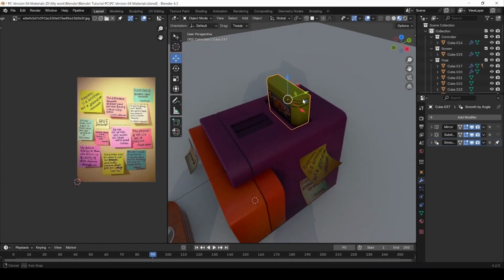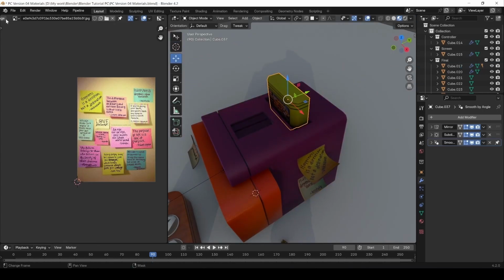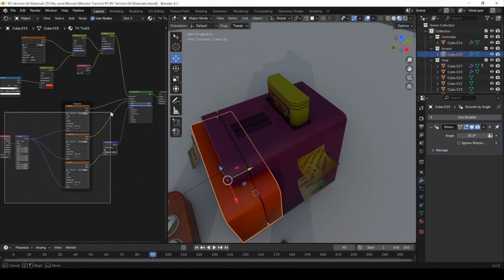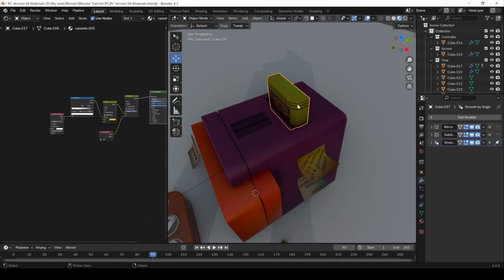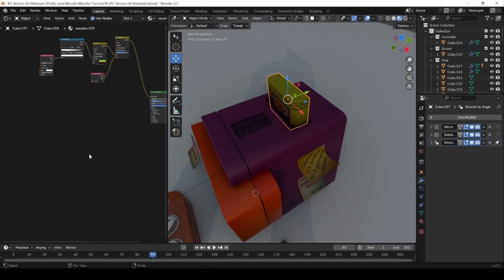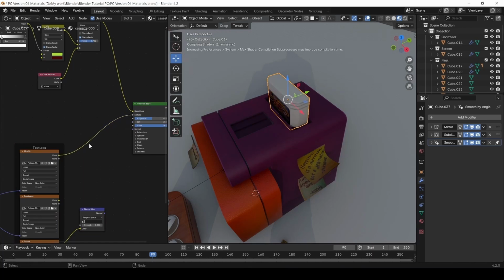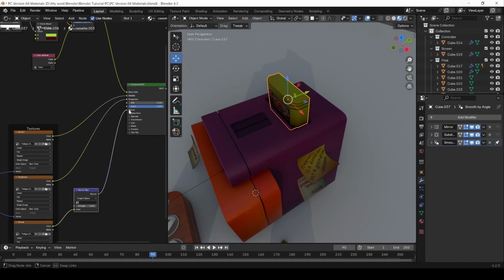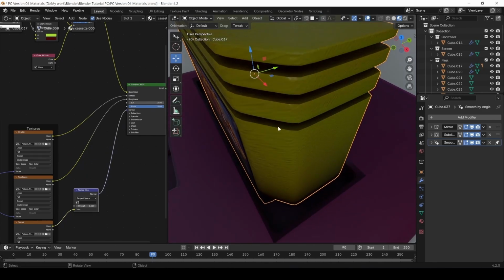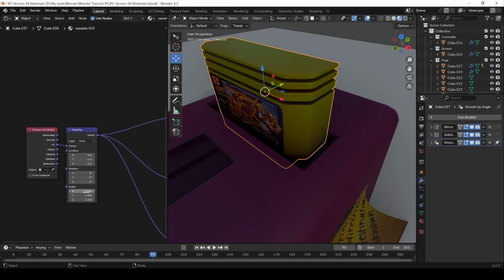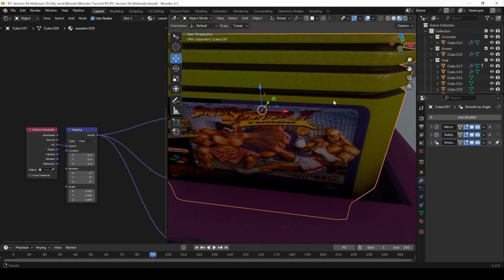One last thing I wanted to show you is, if we choose this and go to the shader editor, let's copy this. You can do it too, I don't know if you did it or not, but I want to do it. Control C, get to this, take all this up, and here, Control V. So metallic to metallic, roughness to roughness, and normal to normal. So it has that pointy effect here. Here let's make it 0, 1 as it was, and just leave it.